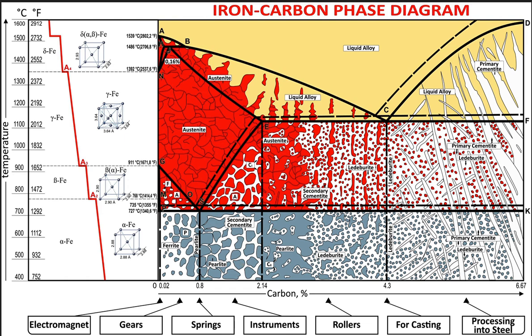And what's the difference? Well, basically cast irons are less rigid, and other things we will hear about throughout our years in materials engineering. But basically, cast irons undergo a different reaction at higher temperatures called the eutectic reaction, where liquid transforms into a mixture of austenite and cementite called ledeburite.